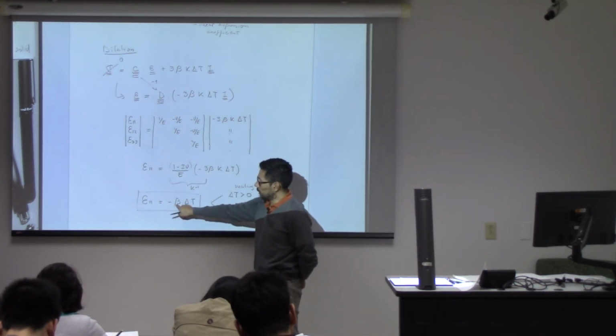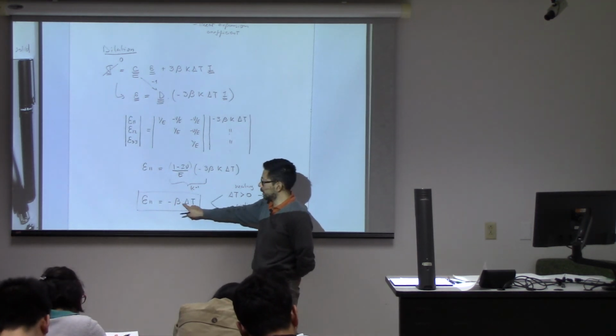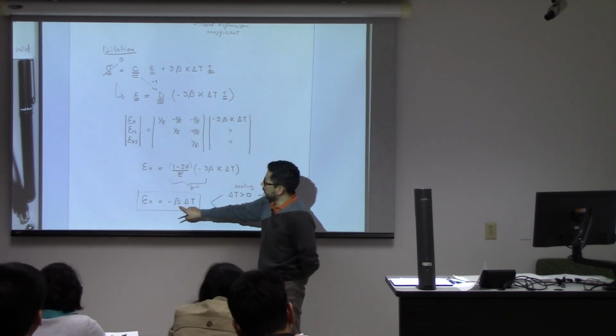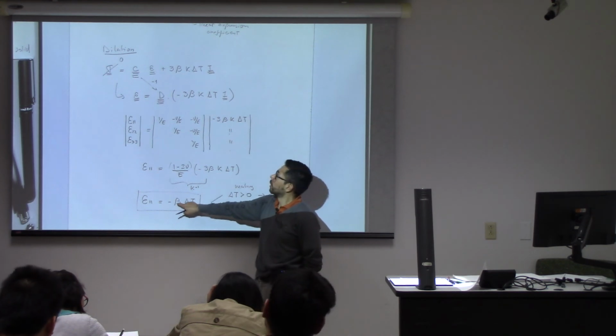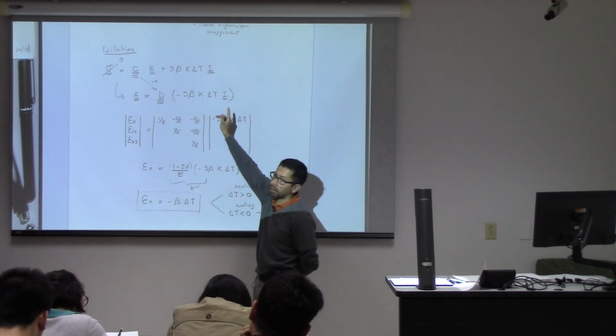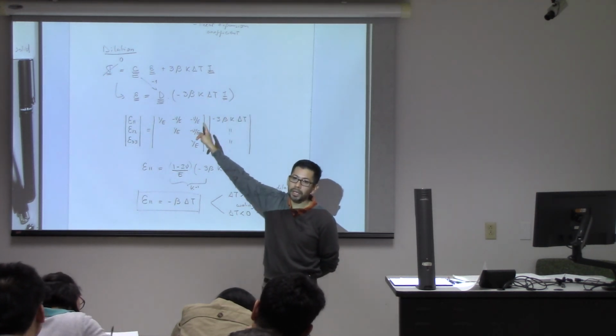same linear coefficient, and it's called linear because usually you just do it in one direction, this linear coefficient of thermal dilation is, in order to put it into our 3D elasticity equation, has to be accompanied by a 3 over there. Sometimes that's not clear in many books.